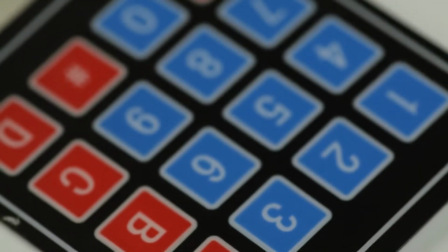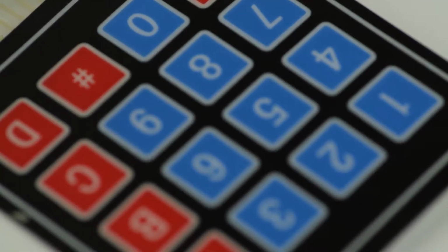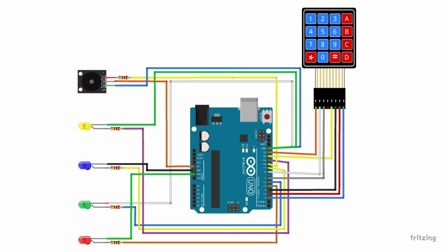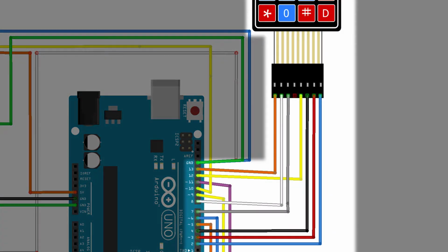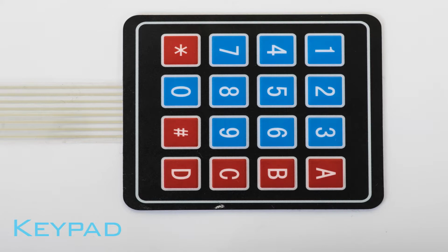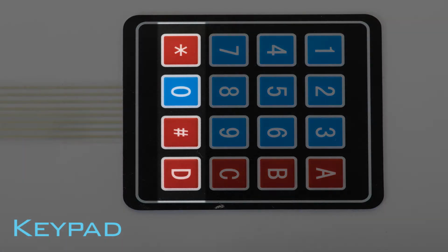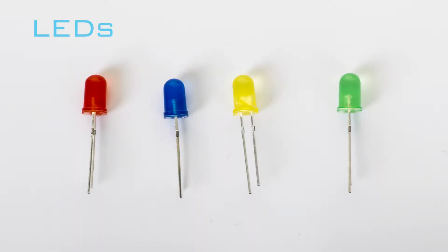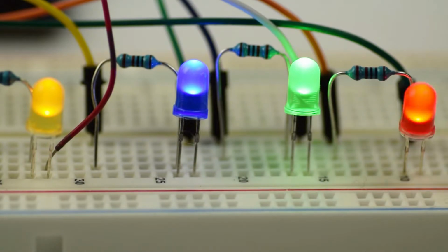To create the memory box, we've used several components. The first one, the keypad membrane, was connected to the Arduino board through 7 digital pins, each controlling 1 row or column of buttons. Since our device utilizes only 8 buttons in total, the last row is disconnected, making room on the board for other components. We've also used 4 different colored LED lights: red, green, blue, and yellow.